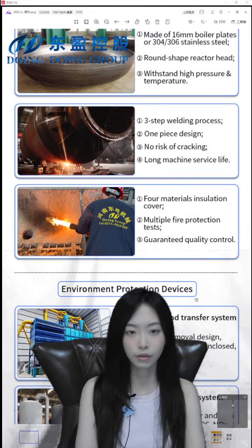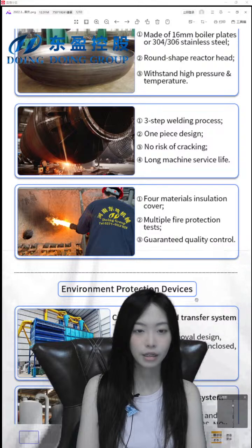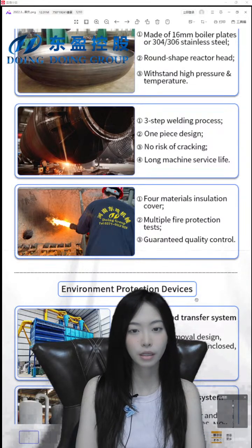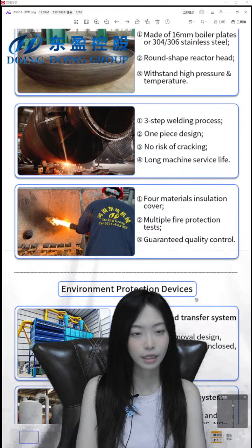If your raw material of plastic is pure PP or pure PS, then the oil yield can reach very high, up to 90%. But if your raw material is something like paper mill waste, daily waste or construction waste, then the oil yield depends on your different raw materials. If your raw material is daily waste, there may be some non-plastic material, rocks or bricks in it, which will influence your oil yield.